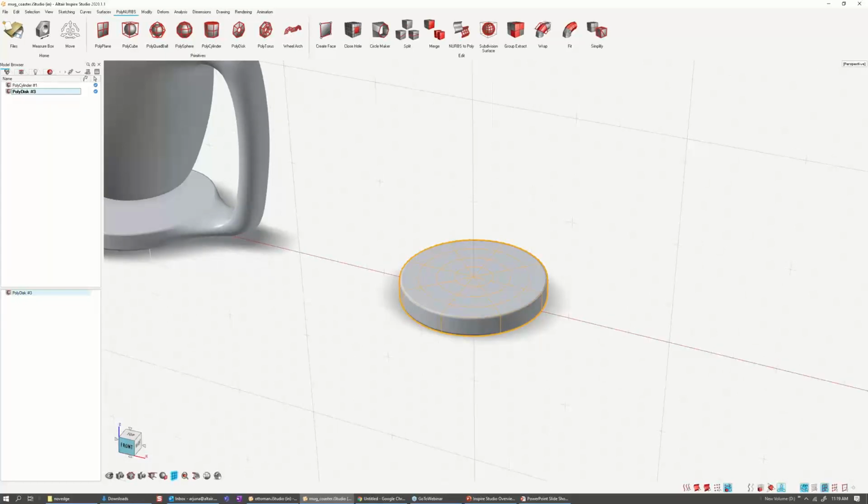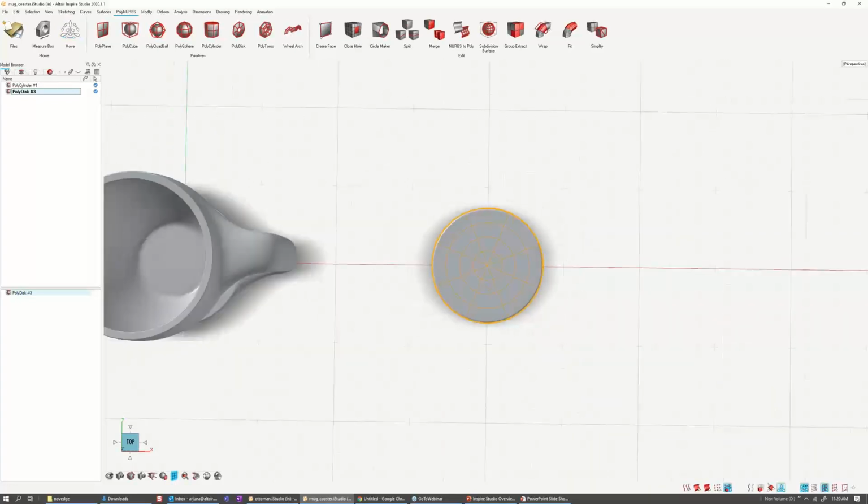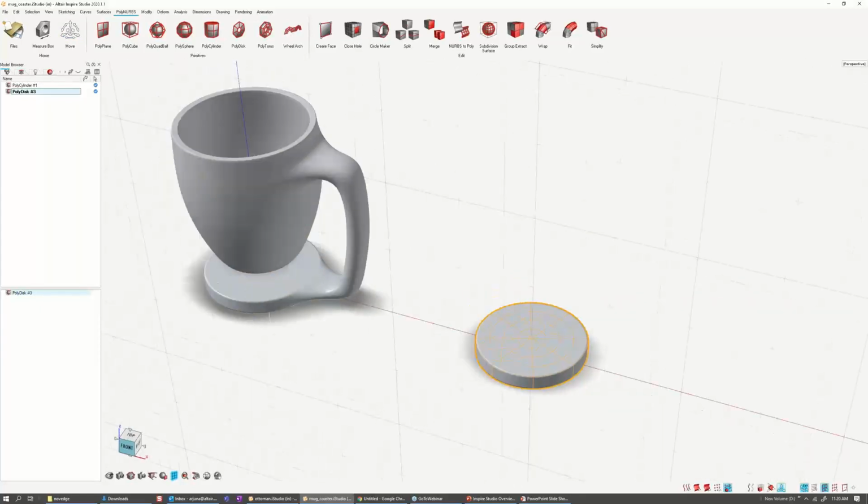And then in order to actually continue modeling, what I can do is I can start off with the same polydisc to create the top of the mug, or I can use some other primitive. So before we do that, let me just quickly rotate this model by about 20 degrees. I'll tell you why in a minute. So since this had 8 pies, 360, every angle is 20, and I just rotated it by 20 so that it's in the center here. Once I have this, I can think about how I can design the top part of this mug.